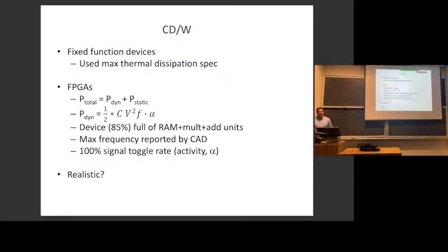It's because you can't turn the transistors fully off anymore. So when you add up 10 billion transistors times a little bit of leakage, it turns into a reasonable amount of power. But you just get a spec. Static power strongly depends on temperature. Transistors leak a lot more as they get hot. That's all included in the spec. They'll give it to you at a certain temperature. You take the highest temperature that you're ever going to use this at. If you know you're going to use it at a lower temperature, your static power won't be as big.